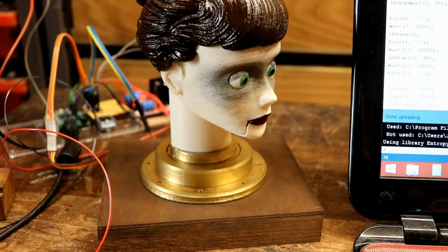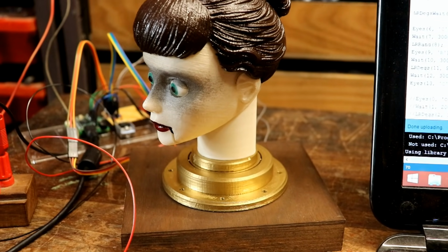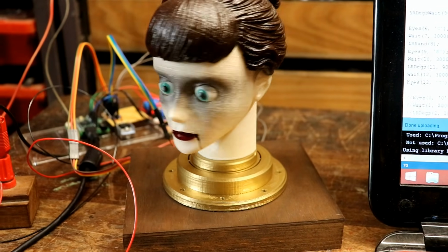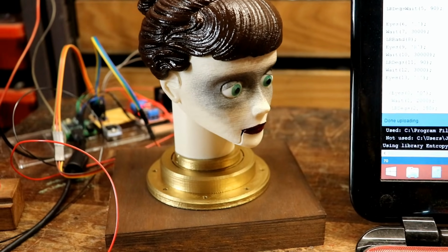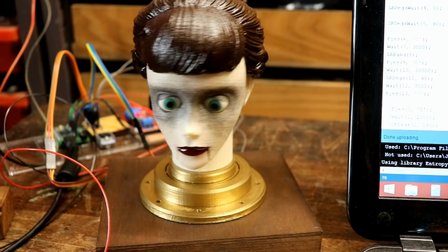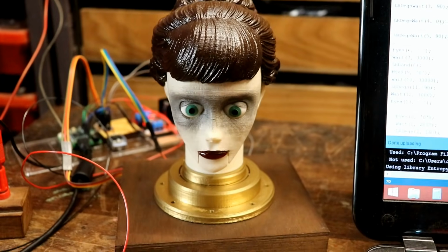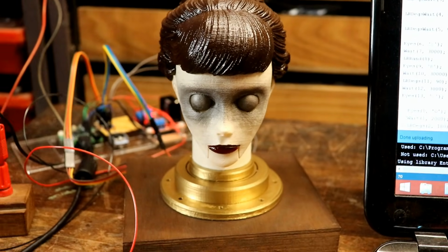And I'm using the fantastic Teensy entropy random library because that actually adds proper randomness by timing the difference between the internal hardware clocks and the Teensy, apparently, because otherwise you just keep reading the same random numbers off the stored list inside, and she'll do exactly the same thing every time. So there we have it. That's exciting. The thing is, once I start, I just can't stop, because the next thing to do is to think about programming the speaking and things, which I said I'll get onto in the next lot of instructions.